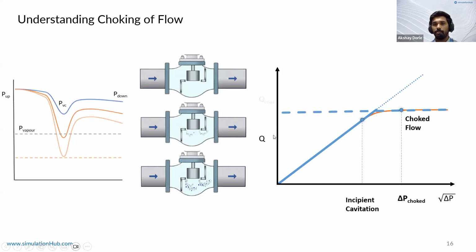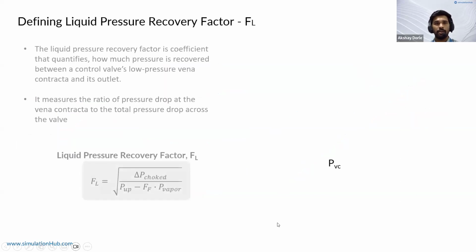And if we plot it, we would get the maximum flow rate through this valve, where the maximum flow rate and the ideal CV curve intersect. That is where we have calculated the FL. So this intersection we would refer to as FL.